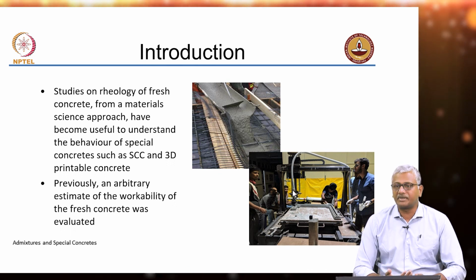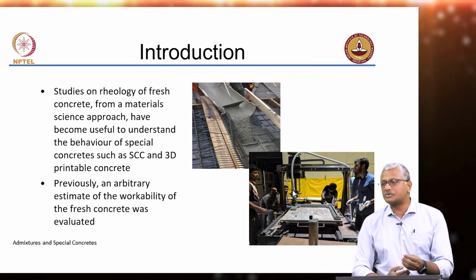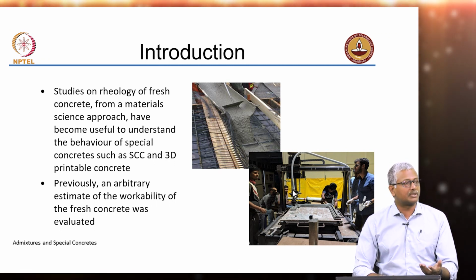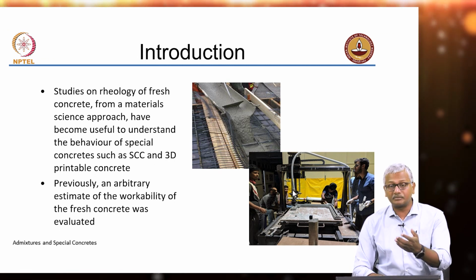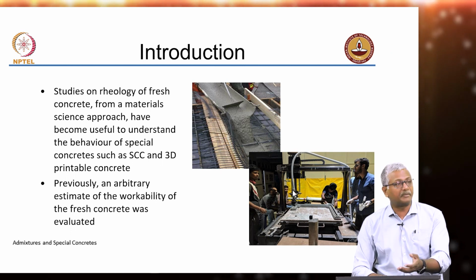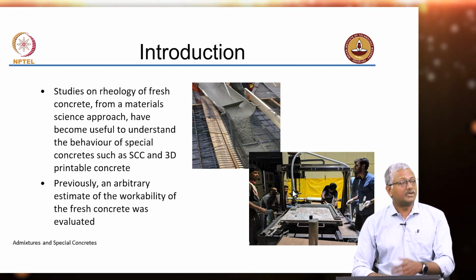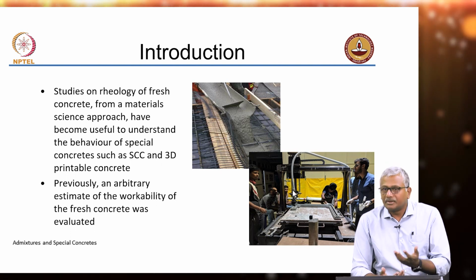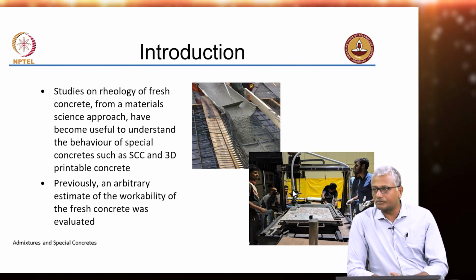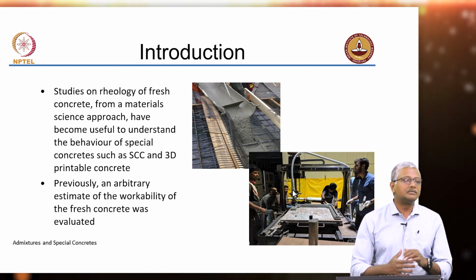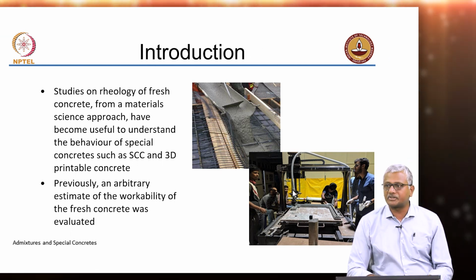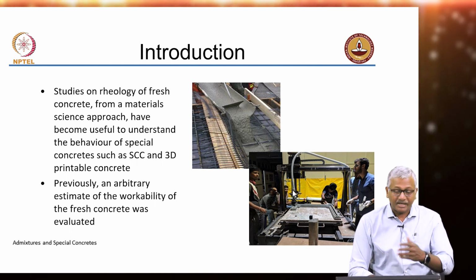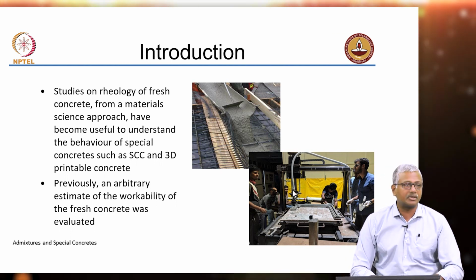When we do a slump test, we are not exactly capturing everything that workability represents, right? If you look at the official definition of workability: mixing, transportation, placement and compaction and finishing. So, all of these aspects you are trying to measure with just a slump test. It's not something that is really capturing all of those things. There are more fundamental aspects to the concrete beyond what we measure with just the slump test. Because of that, we try to study the rheology of the system.